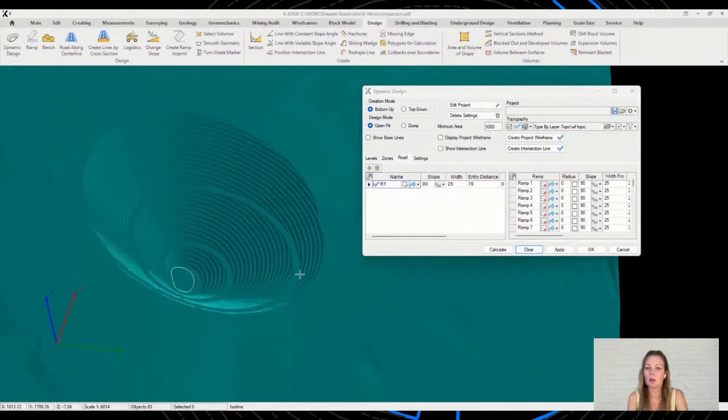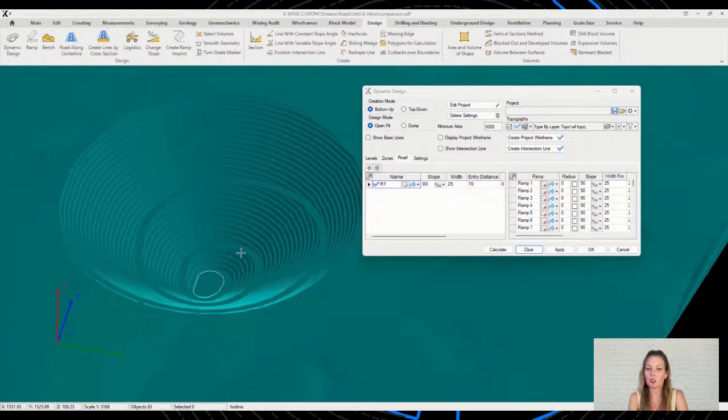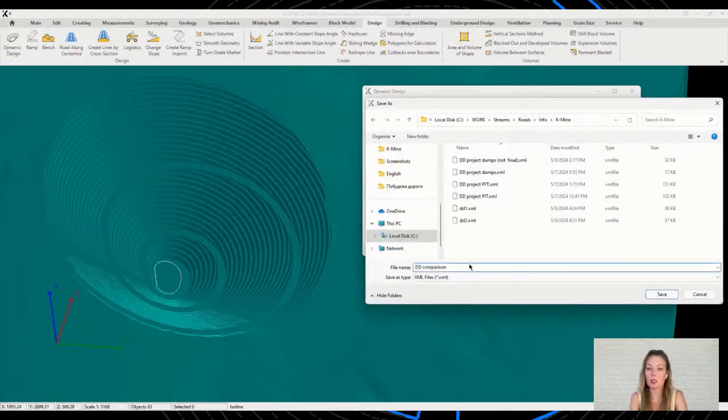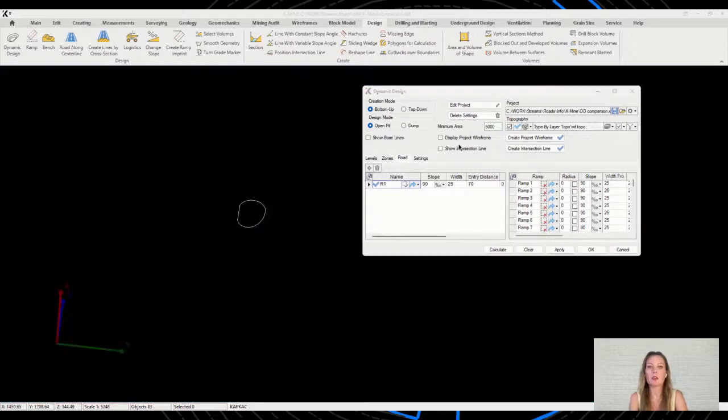After clicking the Combine Project and Topography Wireframe button, we get a project that takes topography into account. This is how, with simple manipulations, the required result is achieved, which could take a lot of time to obtain when using the manual method. Now the project can be saved, and when loading it, you can build the baselines that take part in the construction.